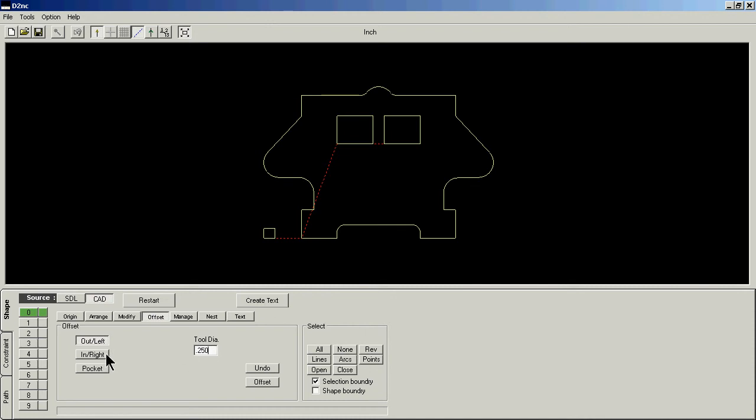and then I made it. I clicked on inside, and I decided since the height from the top to the bottom is the same here as it is on these two holes, and I decided to do them all at one time. And the mistake there was that at that point I didn't have control over what would be machined first, second, and third. And the computer, after watching the video, had decided that it was going to machine the outside of the part first and then cut the two holes, the two square holes.